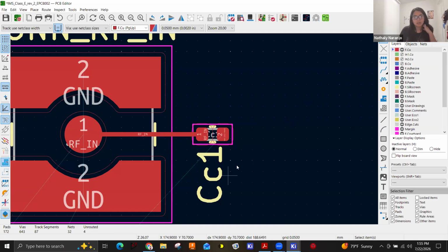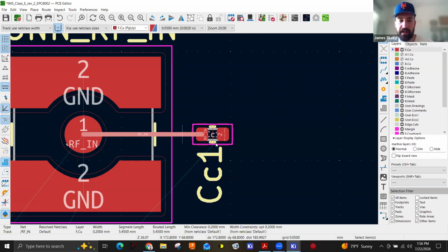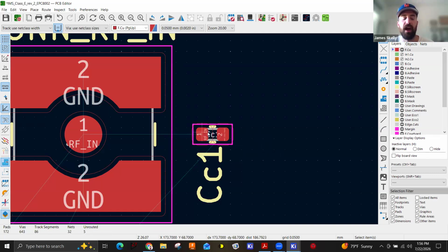Okay, so really the goal of the PCB design is you build the schematic, then you assign footprints to all the parts. You open the PCB editor and you pull all of those parts in, but they're just going to kind of be all over the place, like I said, not connected, kind of like this. And then once you have connected all of the blue lines, you're done. That's what you have to do. And then you order the board.